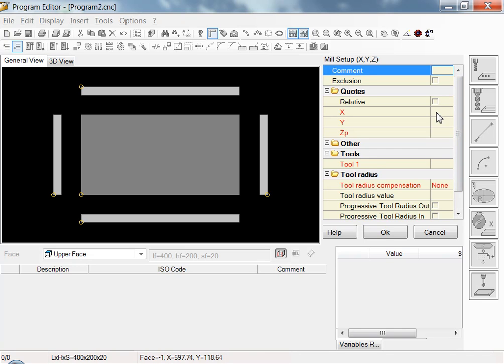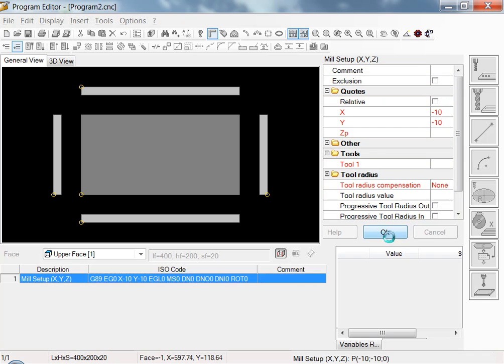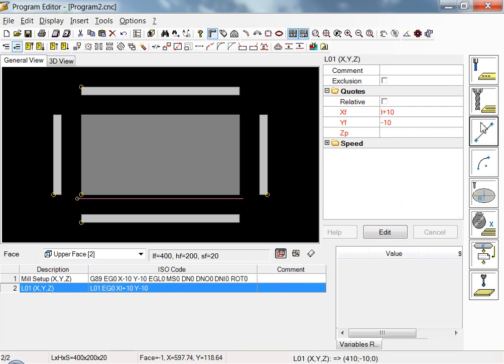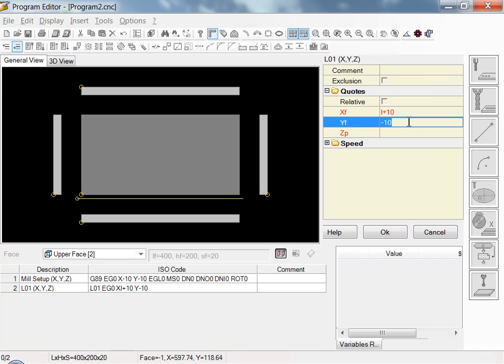a toolpath like we normally would. And let's make it start outside the panel. We don't need to use a tool number or depth because we're just creating geometry to create the boundary to tell the tool where to stop and start. So we'll make a boundary around the part using parametric values.